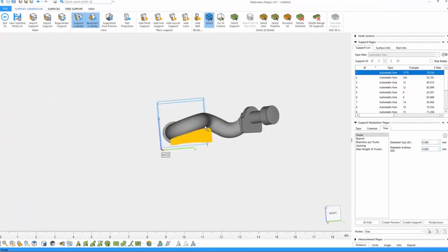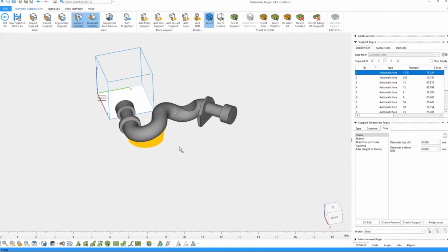So Magics is a very powerful tool. You can do a lot of different editing functions, modifications, things like that. And that's all done to STLs. You can import CAD files and other parametric models into Magics. There's an import module upgrade you can have, so you can import most everything in, and Magics will convert all of those files into a mesh so that then you can do whatever kind of editing you want, whether it's the complex supports or structures or something like that, texture mapping or texture wrapping. Or you can just have the STL file and apply all those things, which usually when you have an STL, you're kind of locked out in what you can do.